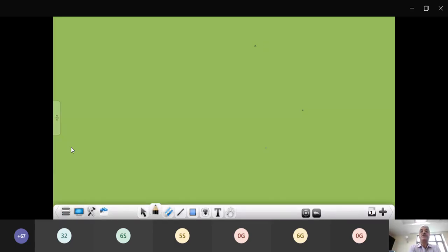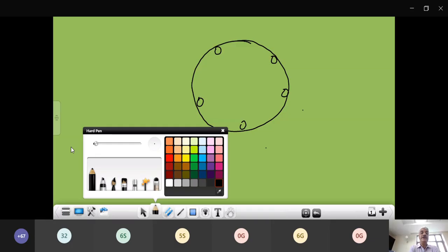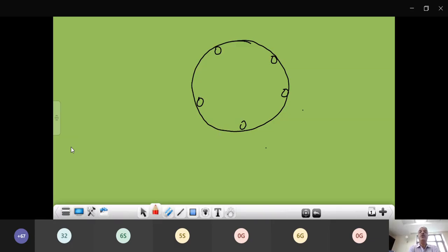If you see the cross section of your pile, let us say this is your ring, these are the reinforcement bars. What you do is you normally provide 4 tubes of 25 to 50 mm, 50 mm is very common, and tie them properly.